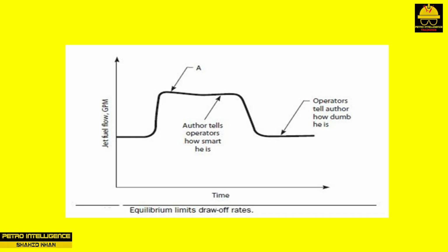Overcoming nozzle exit loss limits. An engineer once tried to increase the flow of jet fuel from a crude distillation column by opening the draw-off flow control valve. Opening the valve from 30 to 100% did not increase the flow of jet fuel at all. This is a sure sign of nozzle exit loss or cavitation limits.